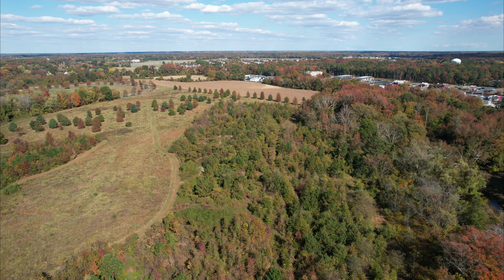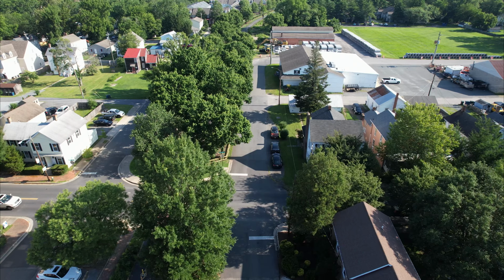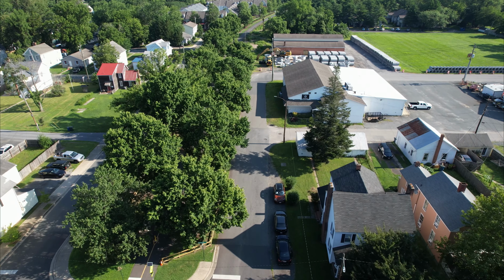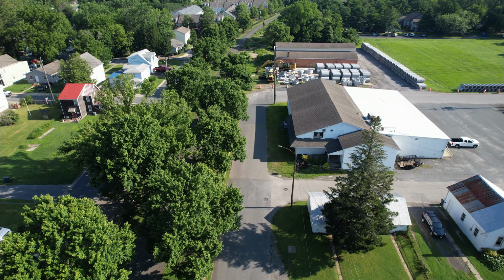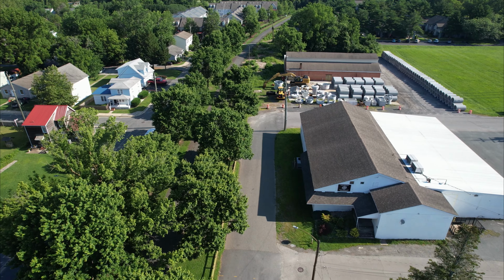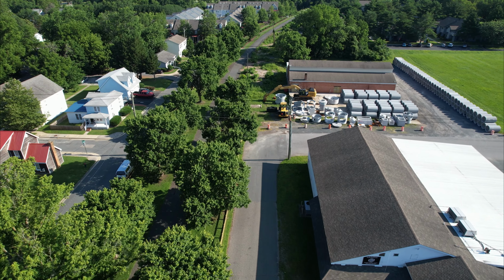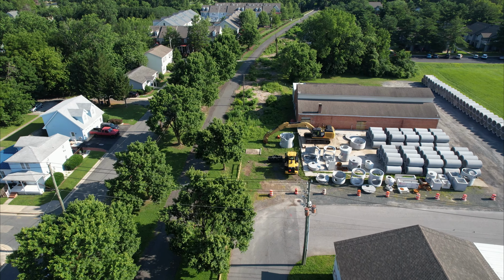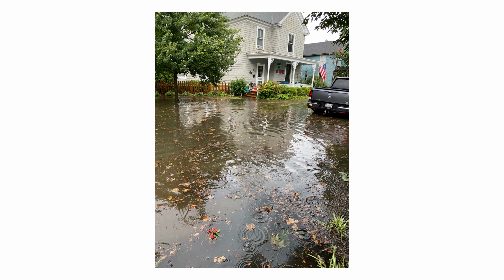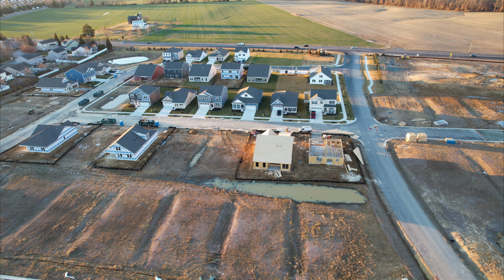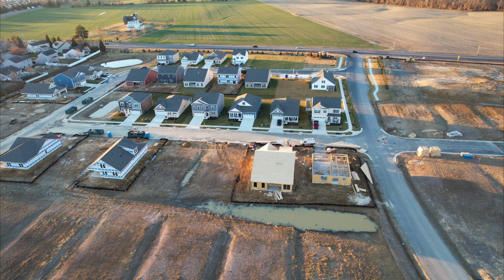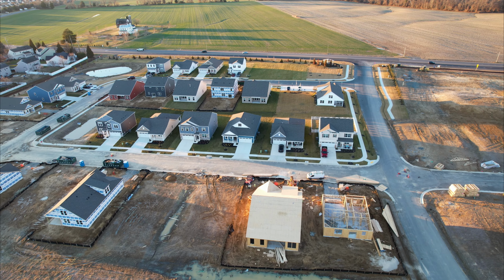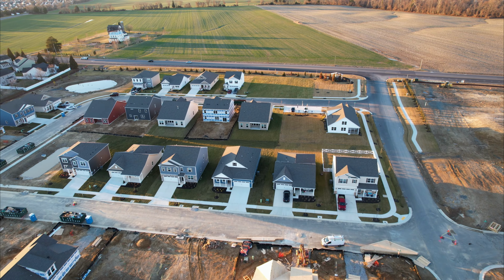Ultimately, this means that in a developed area with a high impervious surface area, like the East End, the potential for flooding is high, as the water reaches and enters the storm drain system more quickly and at a higher volume. If not designed to accommodate these large volumes of water, the storm drain system can be overwhelmed, leading to flooding. Over time, the development of new land puts increasing pressure on any given storm drain system.